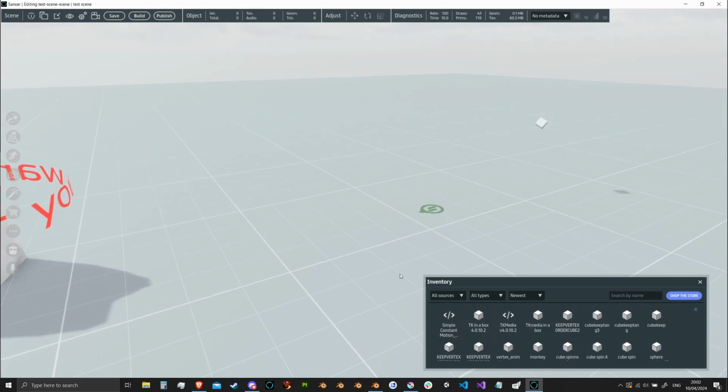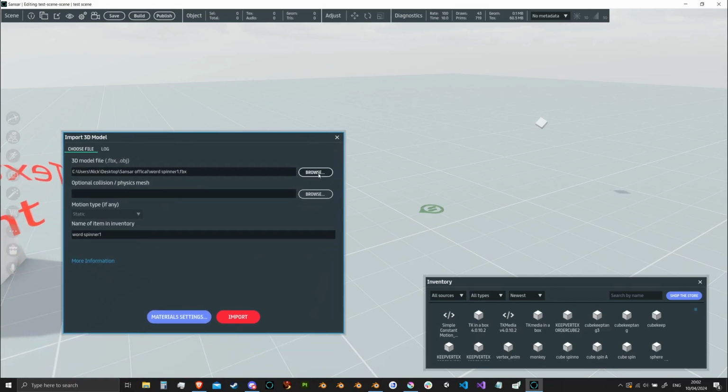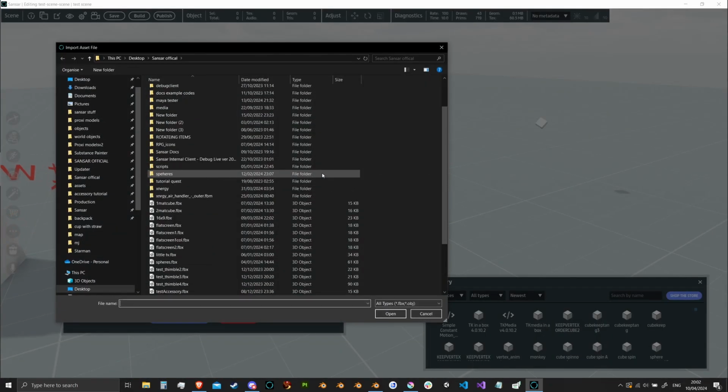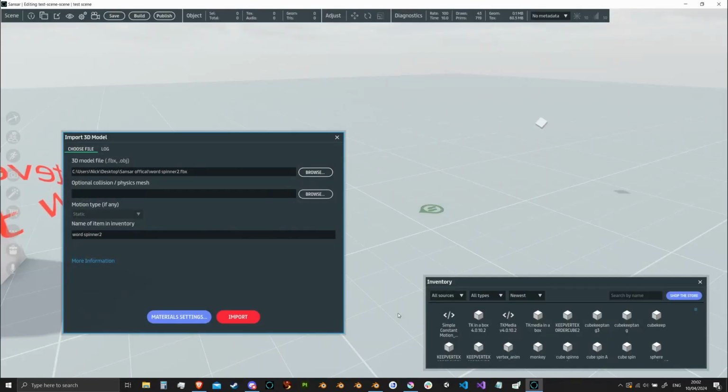In Edit mode of Sansar, at the top Import Objects, select our FBX file we just created and hit Import. This is where you could add collision if required. As we are able to edit materials later, we will set them up once imported.